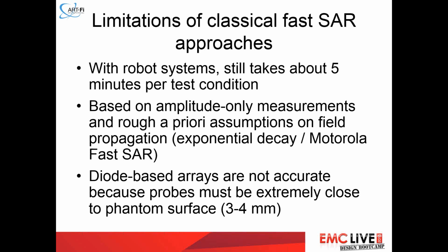Also, another point is that fast SAR approaches based on amplitude-only measurement use rough a priori assumptions on field propagation. A very well-known approach is the Motorola FastSAR, which basically describes the field propagation as having an exponential attenuation with depth into the phantoms, into the mannequin, which means that the field propagates as a single plane wave. It's definitely a very rough description of how the field actually behaves in the phantom.